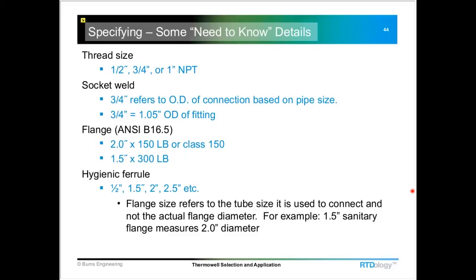And the different flange sizes, and these go all the way up to, I think, class 2500. There may be some other ones there, but usually from the class 150 on up to 2500 would be the most common classes of flanges. And as far as the size, anywhere from 1 inch on up to about 3 inch would cover most of the applications that I run across. There are smaller and larger sizes available.